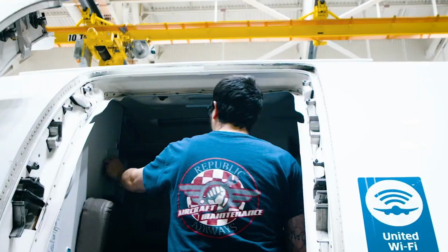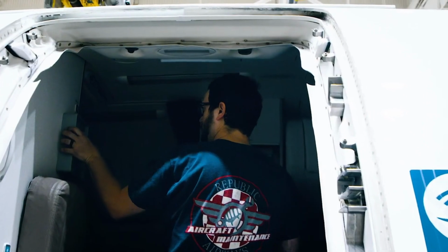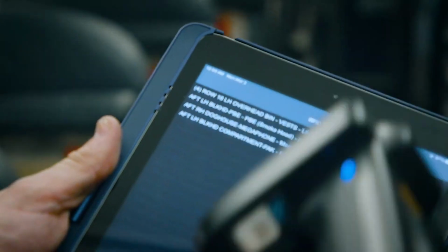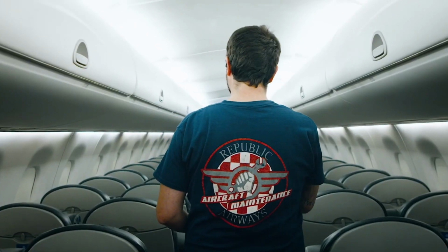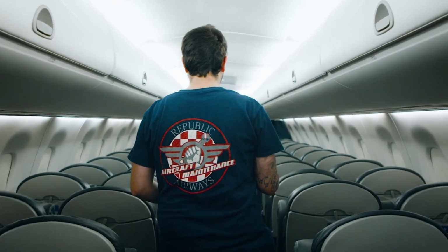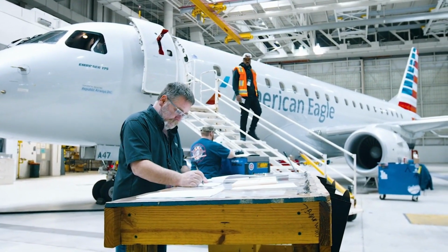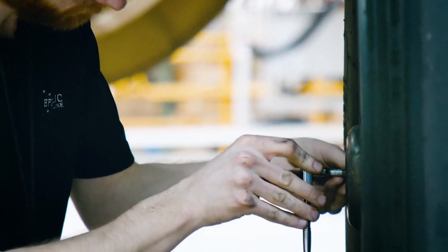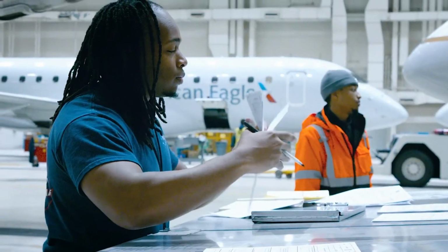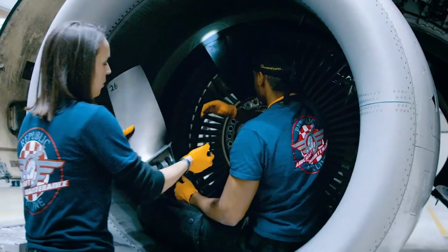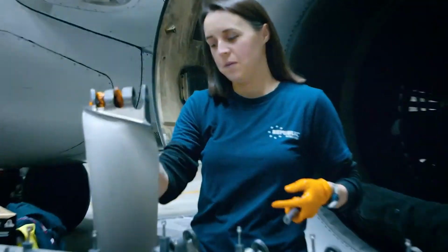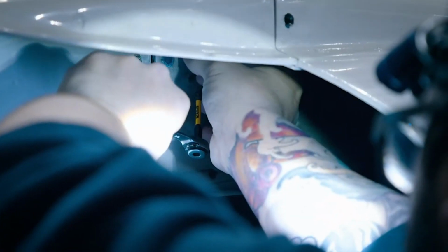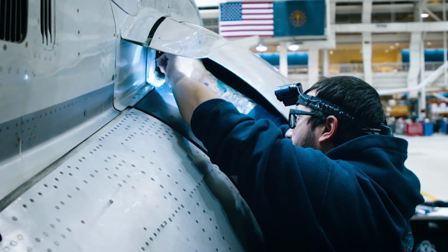The requirements for the maintenance manual are specified in 14 CFR Part 135, Section 135.427. 14 CFR Part 135, Sections 135.415 through 135.417 and 135.423 through 135.443 specify additional maintenance requirements. 14 CFR Part 135, Sections 135.415 and 135.417 are applicable regardless of the number of seats in the aircraft.